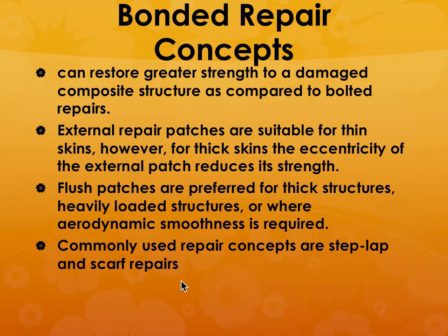And there are repair patches that you can buy from companies like AirTech, and you can make sure that it is the same material as the underlying substrate material, so that you get similar properties. I mean, it may not be 100% back to what it was before the damage happened, but it'll be like 80-90% of the original structure, which would still be okay and acceptable for the structure.